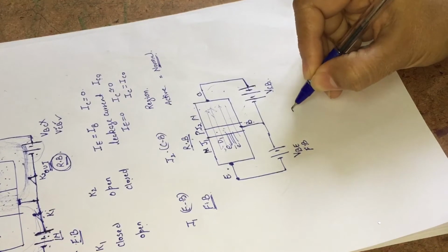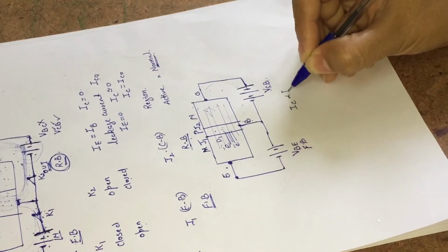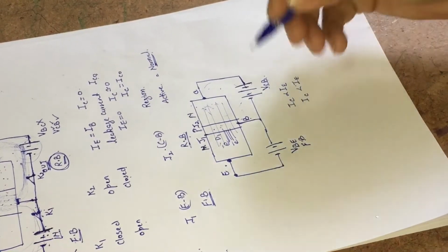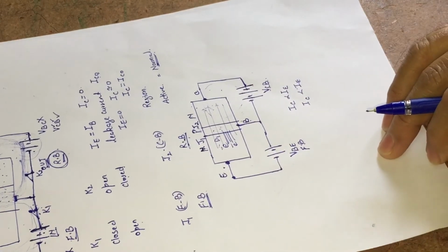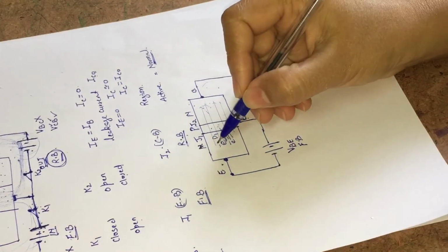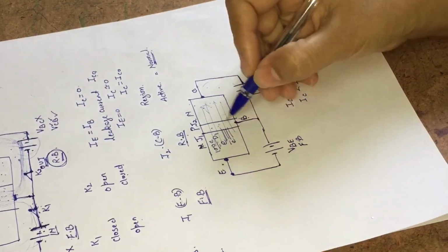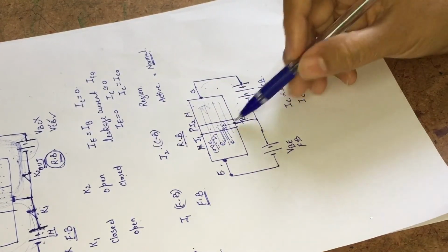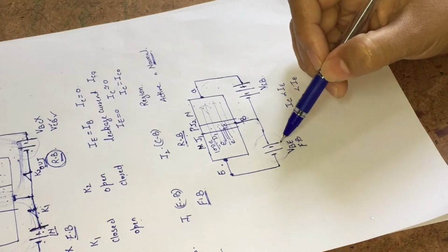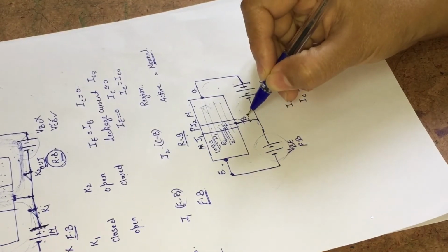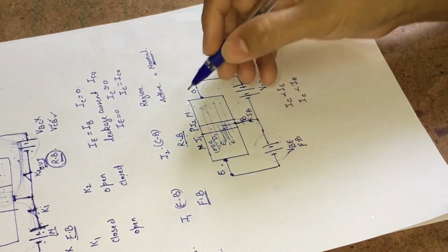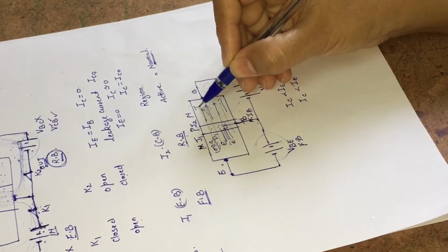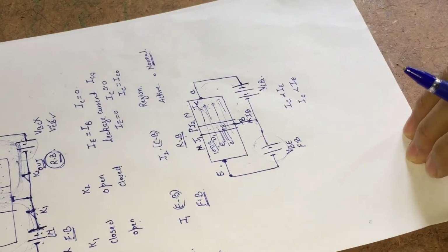Hence, IC is directly proportional to IE, and we know that IC is always less than IE, because in our previous lecture, transistor part 1, we found that if there are 100 electrons here, 5 electrons will undergo recombination, and the electrons which undergo recombination will be supplied by our source, and they will give us our base current, and the remaining electrons will move towards the collector junction and will produce our collector current.